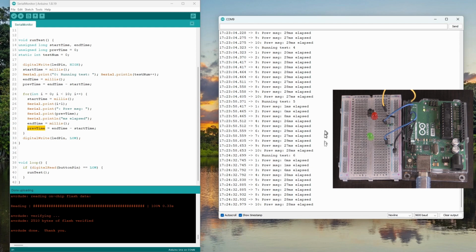Again the reason for that is the first one just copies it into the output buffer and returns, and then the USART starts sending the data off to wherever, ending up in this monitor window here. The next one, there's still some space free, so it only took 1 millisecond. Then it's starting to take a little bit longer as the buffer fills up, and finally the buffer is full, so it has to wait the whole time.